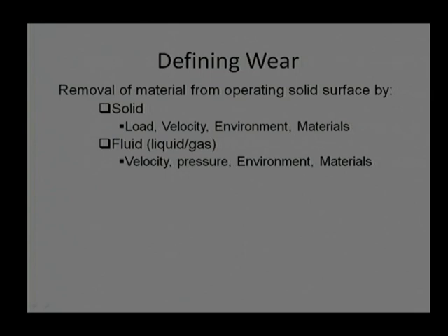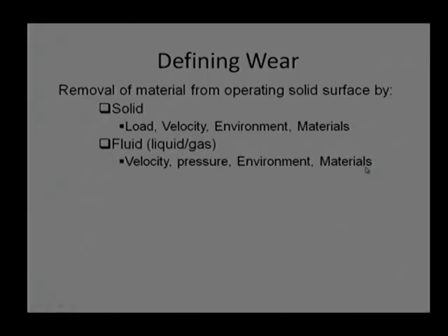If a material can sustain or absorb the wear energy, then it will have a longer life. Many times we say the harder material is preferred, but it is not always the case. Harder material may have lower toughness, lower energy absorption, and many times it will fail at a much earlier stage compared to the softer material, which needs to be studied properly. When we should choose a softer material, when we should choose a harder material, and what is the reason behind that, we will be studying in this topic.